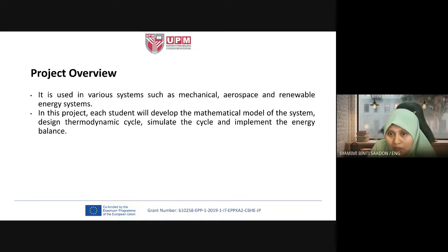And of course you have to sketch the schematic diagram of the cycle, where your boiler, your evaporator, your turbine, etc. are, and sketch also the thermodynamic diagram, TS diagram or PV diagram, and explain the process. Then simulate the cycle; this part I will explain in the next slides. And lastly, you have to calculate the energy balance and the performance.